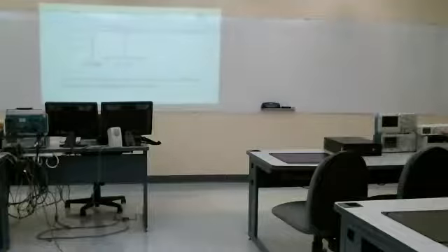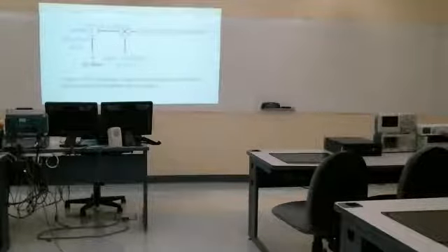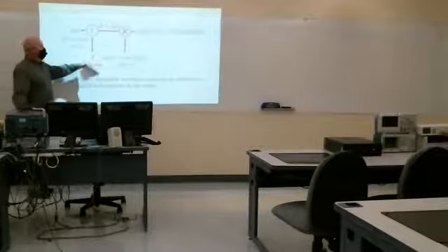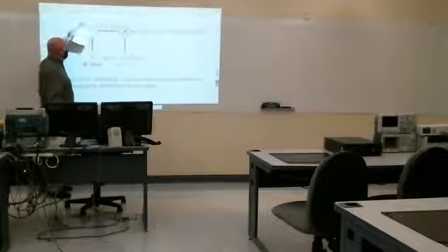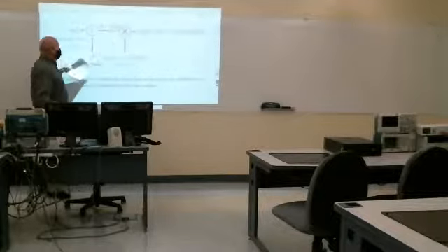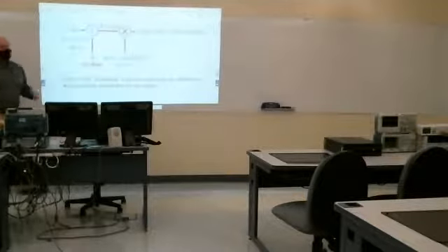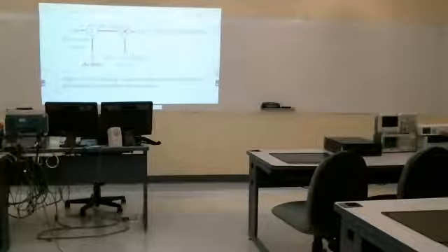Usually, for most signals, it may swing between plus or minus 2 volts or plus or minus 5 volts, whatever, but the minimum and maximum values are equal and opposite in amplitude. This is showing, for the double sideband, we take x(t) and just multiply by the carrier. For AM, standard AM radio, we just add a DC bias. And I'll talk more about why that is done.